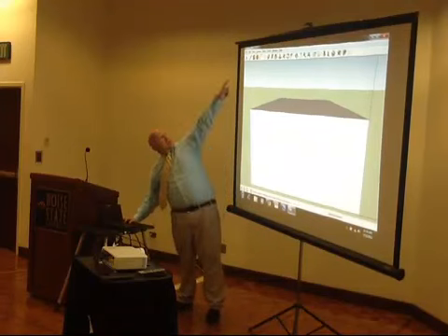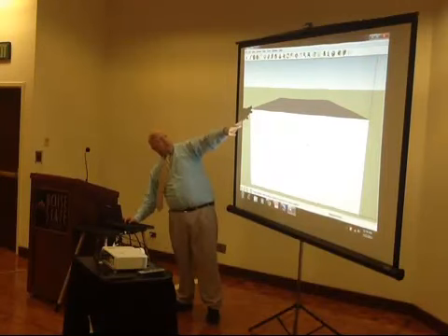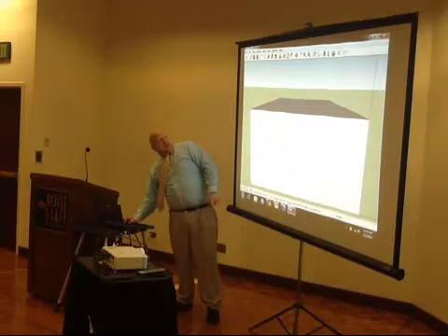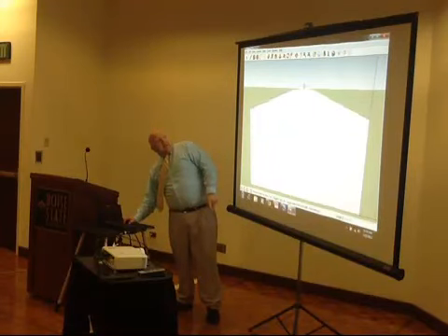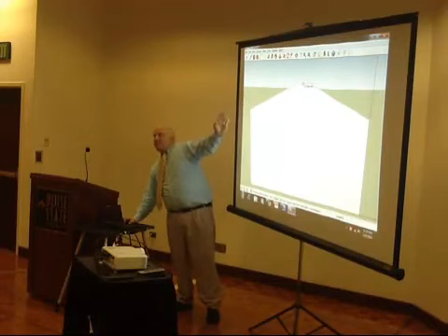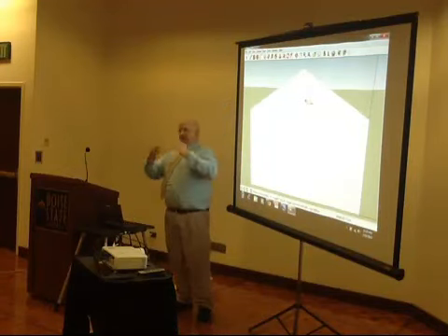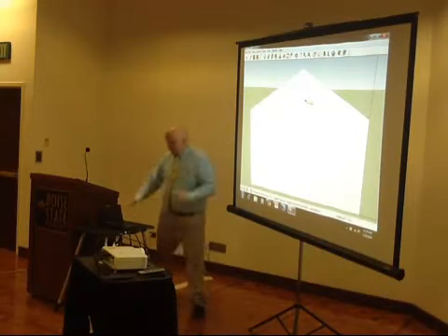So the first thing I want to do is get my Selection tool, click once on that line so that it's blue, then go to my Move tool, and I should be able to drag. And as I drag, you'll see that I can snap to the blue axis, which is vertical. And if I stay on the blue axis, then I'm not going to have a skiwampus gable.